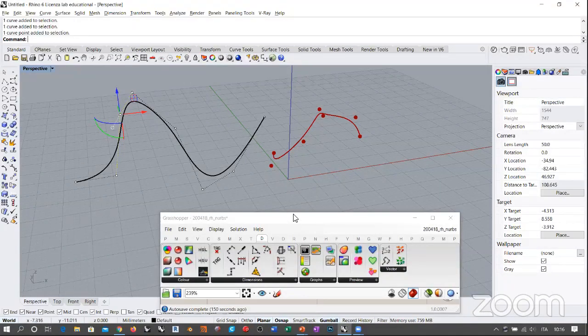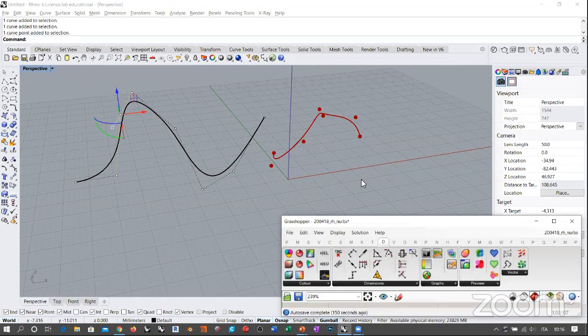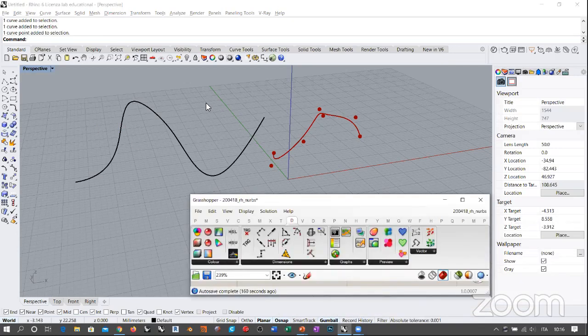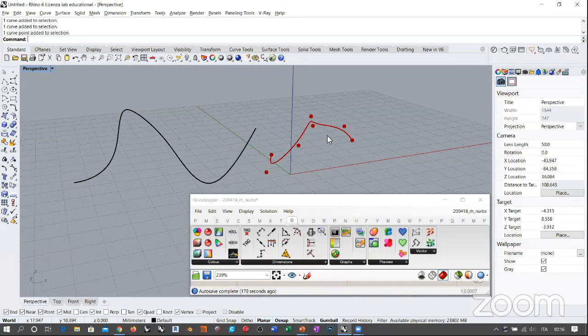But when you switch, for example, when you start working with Grasshopper, something happens, and this is the main problem for many users. Something happens because Grasshopper is not based on the geometric aspect of NURBS objects. It's based on parametric representation. And we are talking about a different parametric meaning. So parametric means that basically all the design that you create is based on parameters, okay? But in this case, I'm talking about a different thing, which is the parametric representation of geometry.